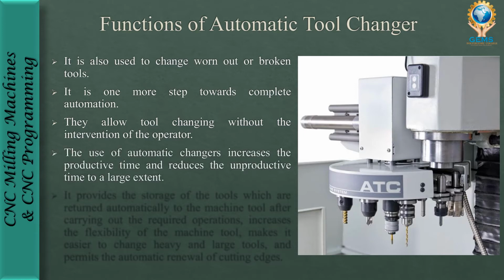The use of automatic changers increases the productive time and reduces the unproductive time to a large extent. Productive time means you can increase the number of products machined in the same time, whereas without the automatic tool changer it will reduce the productive time, by increasing the time used for loading and unloading the tools.